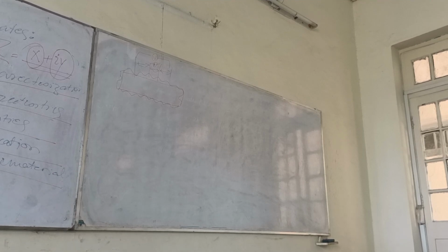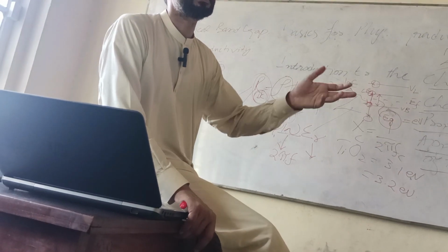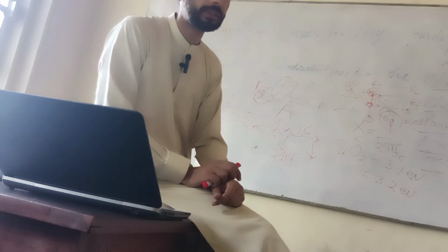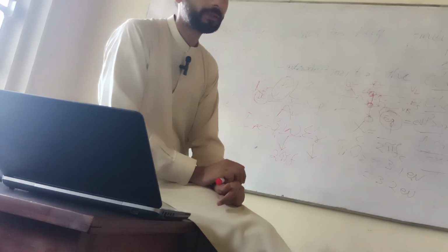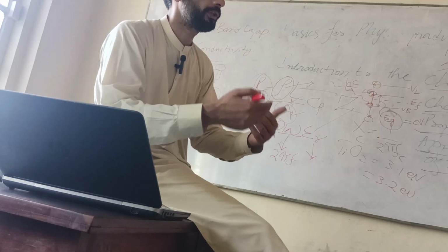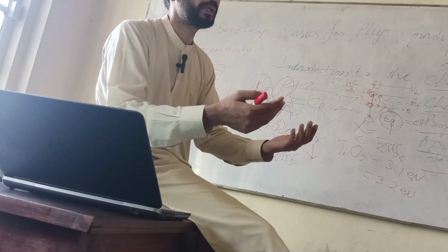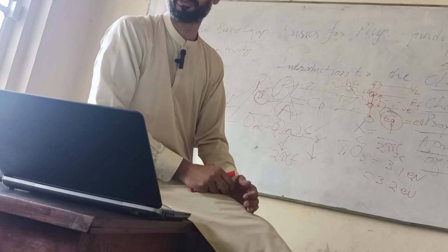There are so many, but the basic ones are what? Impedance, capacitance, not the series capacitance, parallel capacitance, the capacitance because of the dielectric material, not because of the electrode. Resistance, AC conductivity, tangent loss, sometimes called dissipation factor, the energy which is not stored but also not delivered at the output.